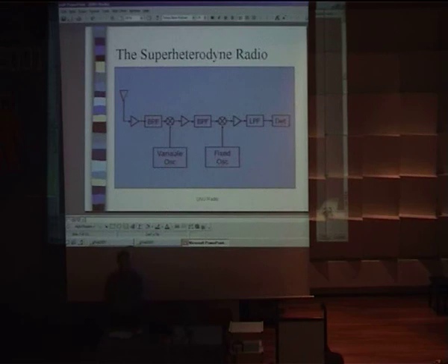You twist this knob, and you can think of the signal of interest as coming down the antenna over here at a particular frequency, so in one sense it's a fixed part. By twisting the variable oscillator, I'm going to get an answer out here that's usually either the sum or the difference that I'm interested in. This piece in here is called the IF, or intermediate frequency, which in these radios you pick one that you like. And there's a bunch of engineering trade-offs to make.